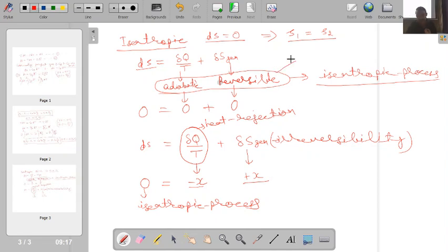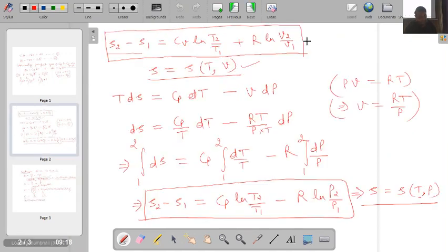So let me repeat once again, though all the reversible adiabatic processes are isentropic, but all isentropic processes may not be reversible adiabatic. However, whenever I will be using this keyword isentropic in this particular course of compressible flow, majority of the time our situations will be nothing but reversible adiabatic. So now let's try to utilize these equations. Say this is equation number 3 and this is equation number 4. So let's try to utilize equation 3 and 4 to derive the relation for the isentropic process.